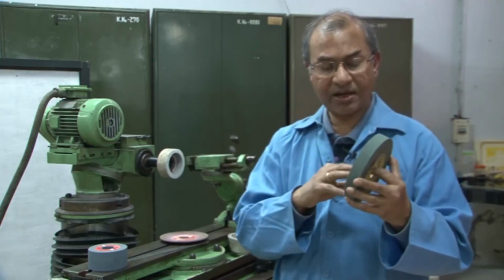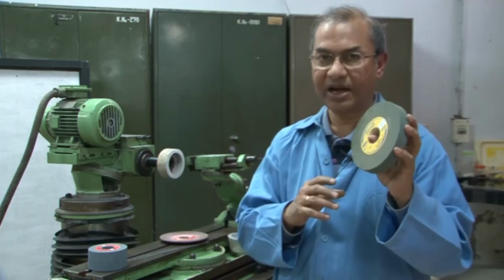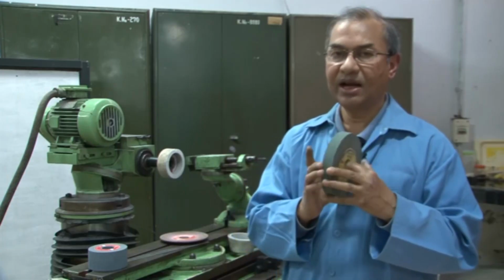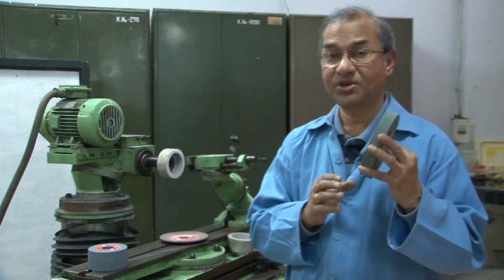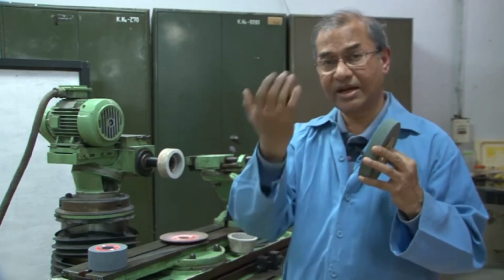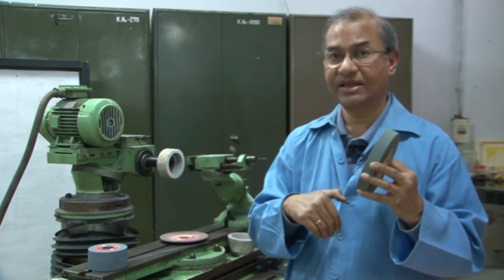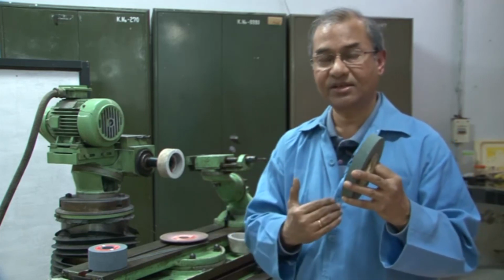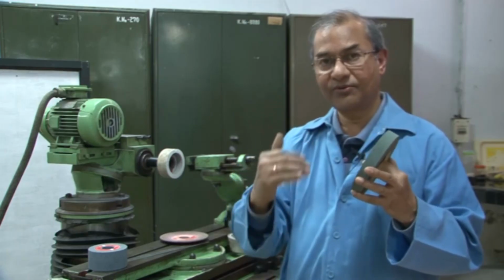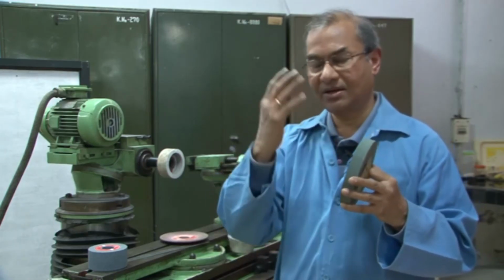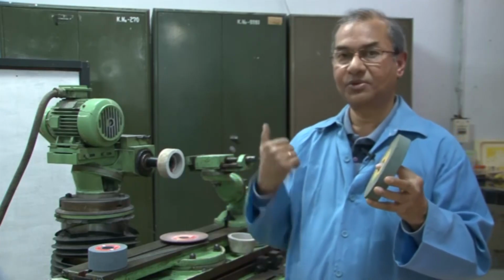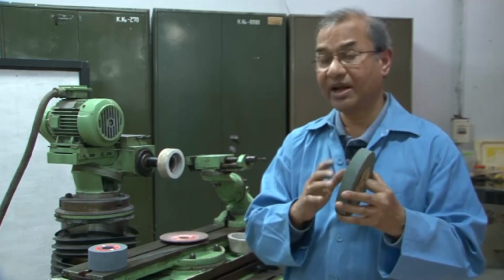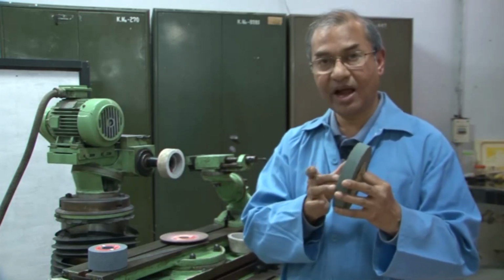So, there are 17 structures of grinding wheels, and that is an international standard. All over the world these 17 structures are used, from 0 to 16. 0 is dense, to open is 16. So, altogether there are 17 structures. 0, 1, 2, 3, 4, these are very densely packed grinding wheels, and starting from 8, 9, 10, 11, 12 and so on up to 16, they are loosely packed, meaning that the voids are very big and the bigger chips can be accommodated there.